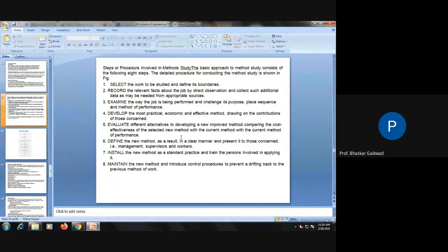By applying repeated blows of the forging press, the material is converted into the required shape using the particular forging die. After that, a trimming operation, then normalizing, then machining, then heat treatment, then grinding. So this is the sequence.